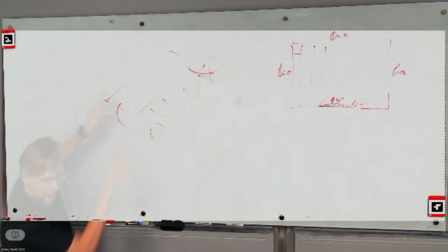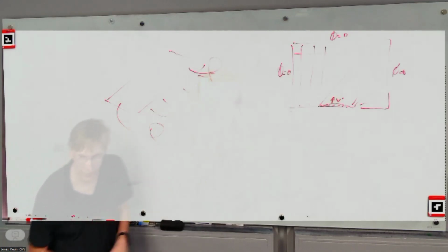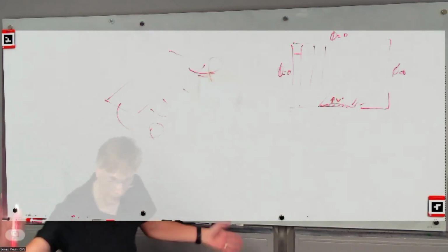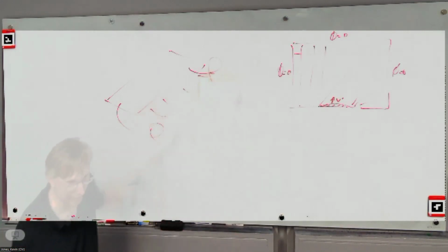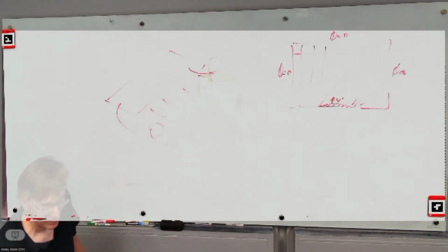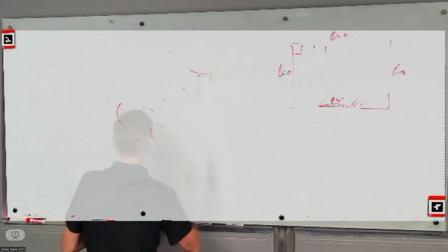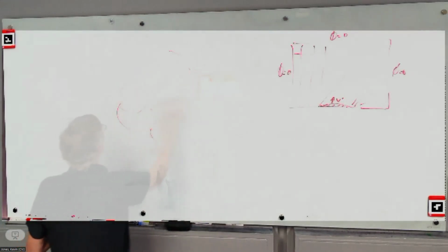But that theory never predicts the stall of the wing, right? I don't know, probably nobody tried it, but you get a value of dCL/dalpha. And so you're just multiplying by alpha to get CL at whatever angle of attack you want. So put in 90 degrees, you're going to get something close to 2 pi. And you're not going to get that in real life. That's not going to happen. So in real life, that wing is going to stall.